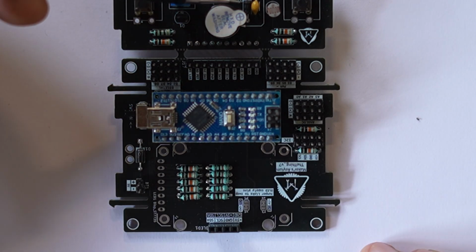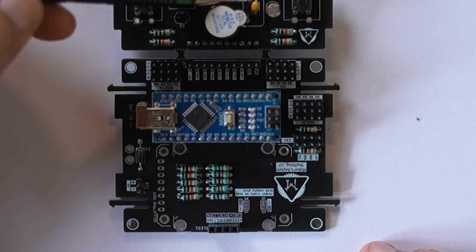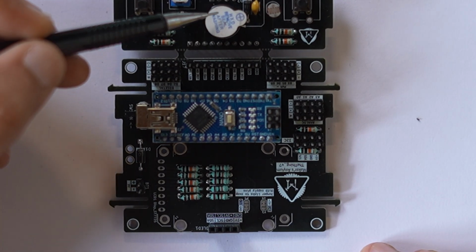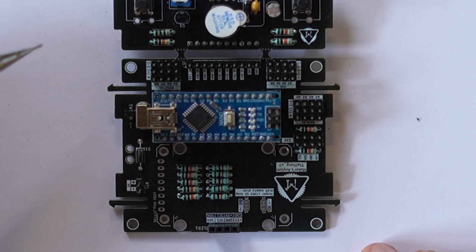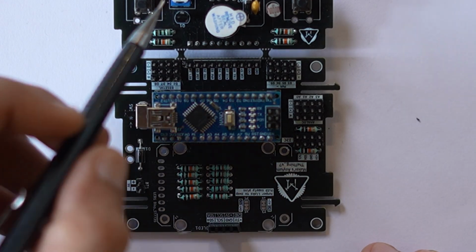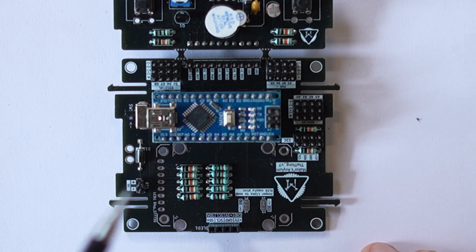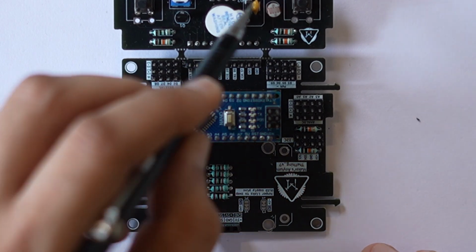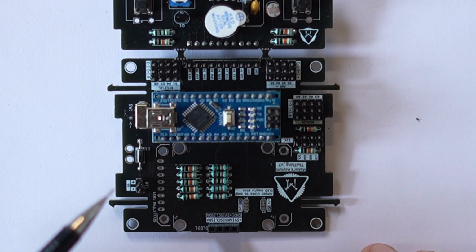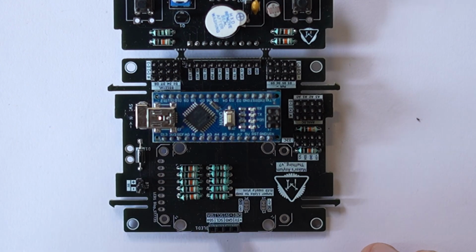There's also a second one here, which is used as a protective function. So this diode is connected across the audio buzzer, and the purpose of the diode in this condition is to protect or make sure that the transistor which is driving the buzzer doesn't get damaged. And this kind of application you'll find most often when you have a transistor that's operating a relay or a big load and stuff like that.